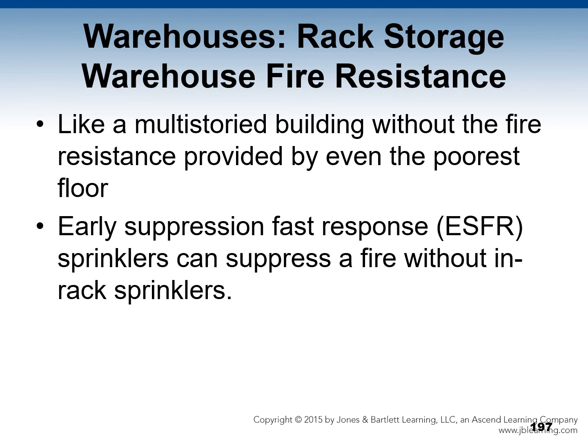In terms of rack storage warehouse fire resistance, like a multi-storied building without the fire resistance provided by even the poorest floor, in-rack sprinklers must be provided at intermediate levels. Early suppression fast response, or ESFR sprinklers, can suppress a fire without in-rack sprinklers. So in these rack storage warehouses, you sometimes have sprinkler systems built into the racks themselves, and then you also have the ESFR sprinklers. Sometimes they can act quickly to suppress a fire, even in a facility without in-rack sprinklers in place.